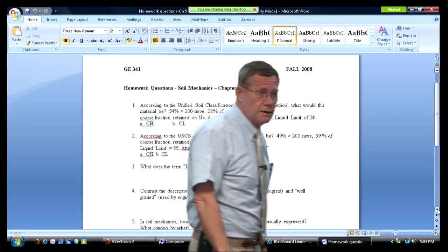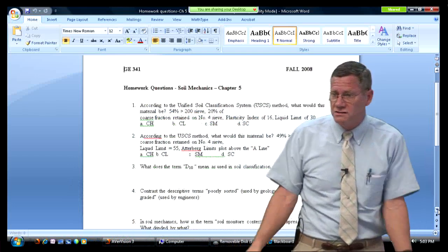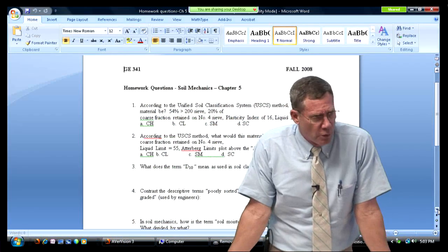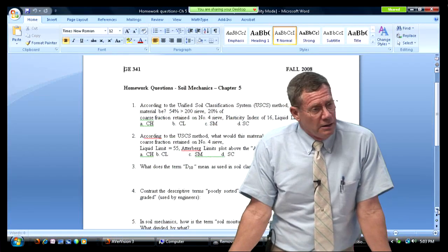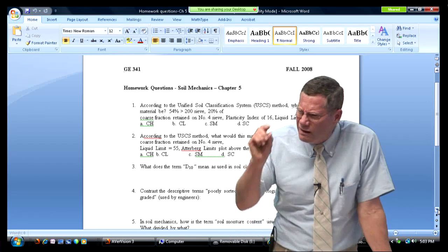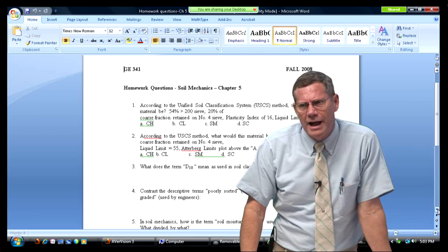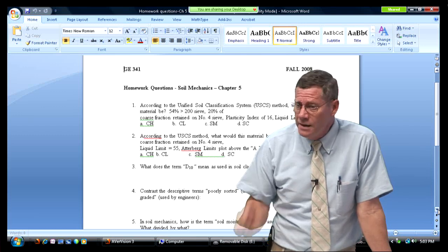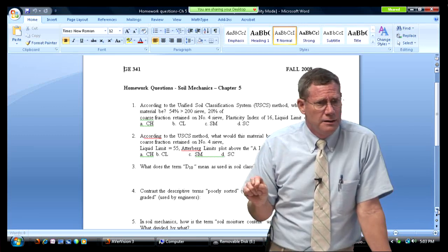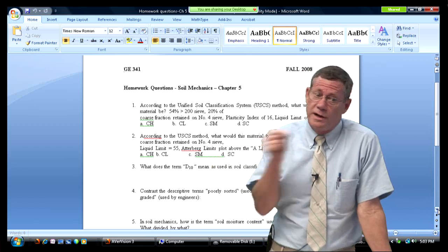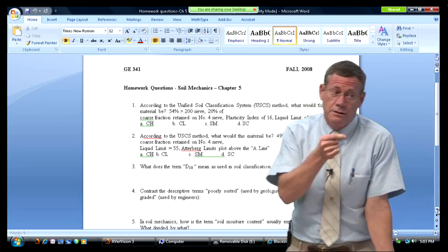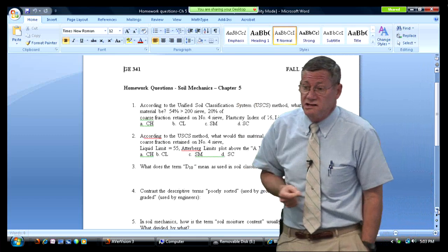It's what happened with the San Jacinto levee failure, California. The Corps project had a 25% flood against it. It disappeared. 25% of the design flow. Did you miss the mark by a little bit? I'd say yeah. Someone missed the mark by a whole lot there. And the problem was that the channel didn't have the material. It was a standard specification in the contract document. It didn't exist out there.